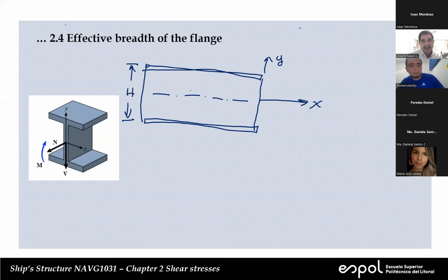Now, in here, you are supposed to have the 3 strain gauges, right? So I have one here, the other here, and the other here. I think this was S1, S2, and S3. I'm not sure about that. So this is at 0 degrees. This is at 45 degrees. This is at 90 degrees. And with these values, you are supposed to calculate gamma XY.